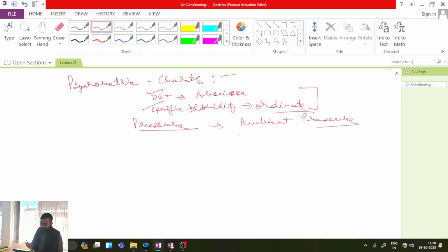So if delta P is very less, in that scenario I can assume that at various locations the pressure is the same, and that pressure is nothing but equal to the ambient pressure. Is this point clear? So that is the reason for the psychrometric chart, whatever standard psychrometric chart you will be finding for moist air, only one chart is available.